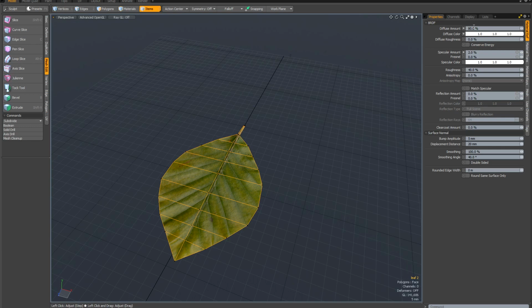And you need to always balance out your values, because if you have 80% diffuse amount and then you add subsurface scattering at 50%, you're going to have a total amount of light being diffused at 130%, which is obviously not physically correct. The values can't exceed 100%. They can be below 100% in case some energy is lost through absorption or whatever, but you can't exceed 100% if you want to have a proper energy conservation.